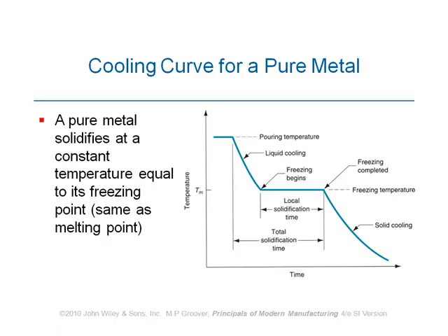Once we put it into the cavity and the mold is filled, it takes some time for the molten material to lower its temperature to melting point first. Then it takes some time where there is no change of temperature, but there is a change of state from liquid to solid. And after that, once the material is solidified, it takes some time to cool down to room temperature. Does it make sense?